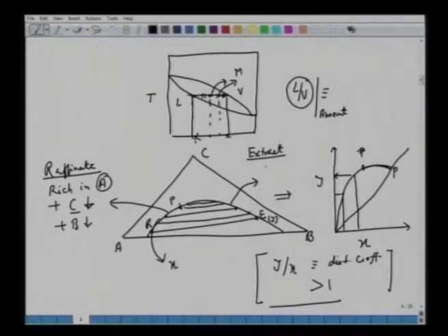That also contains A, B, and C, except it has a larger amount of solvent, closer to this apex. So with a large amount of solvent, C is larger. See, this is closer to C, closer than this point. So on any tie line, this is closer than this. Y is greater than X, except beyond this plait point. Now the slope starts decreasing. So if the slope is like this, now you have it like this, slowly and slowly. Beyond this P, the slope starts decreasing.